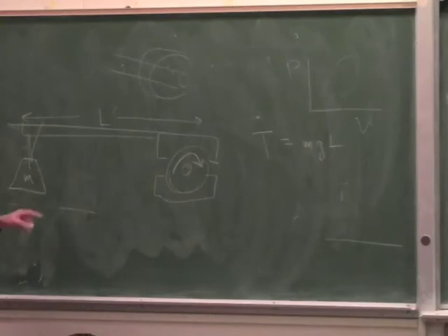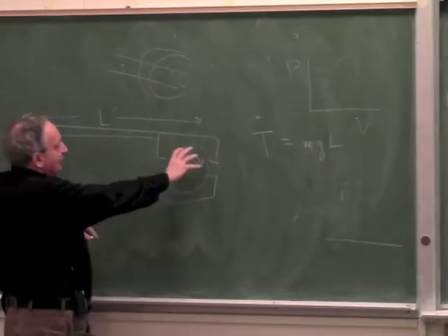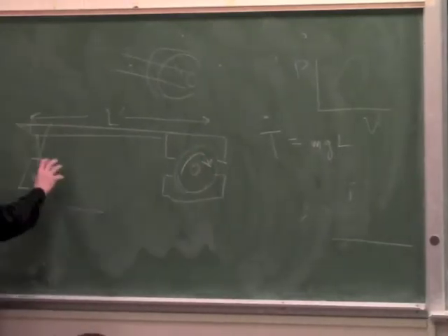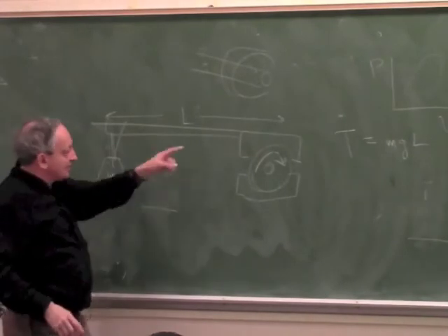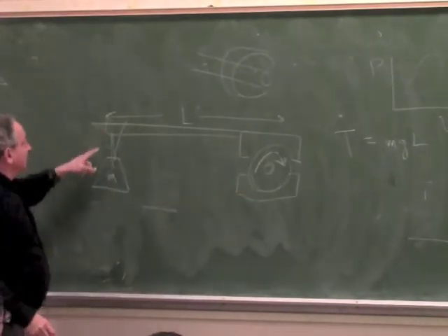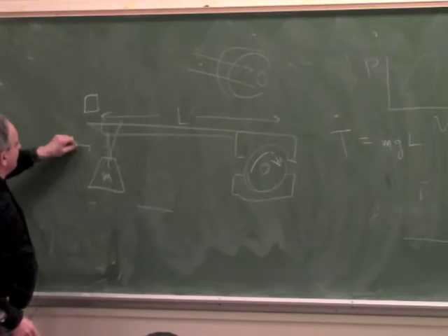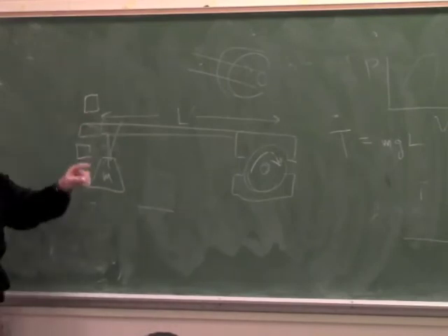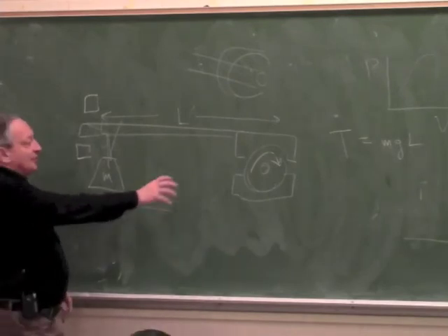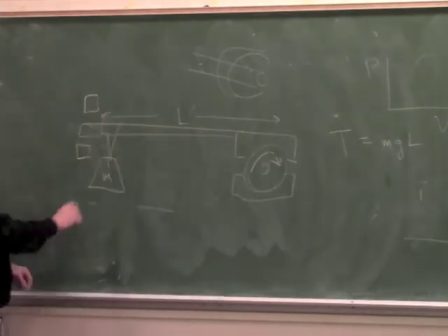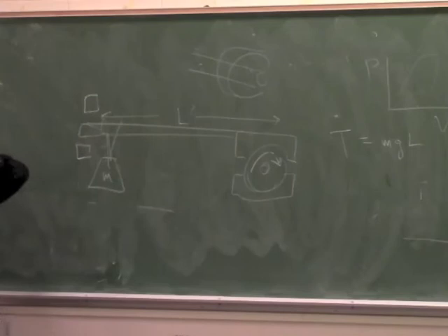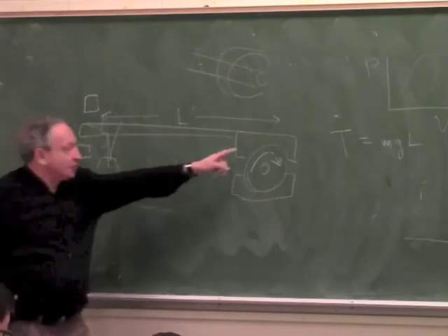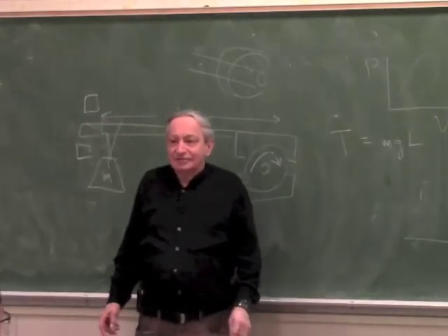Okay. So basically, you wanted a different point, you clamped down the brake more, increased the weight more, until it slipped again. So this didn't move. You had a stop here and a stop here. So this arm had to stay between the stops. It didn't swing around. But you played around for a given friction. You played around with the weight until the arm stayed floating, and then you knew that that friction torque is MGL. Okay?